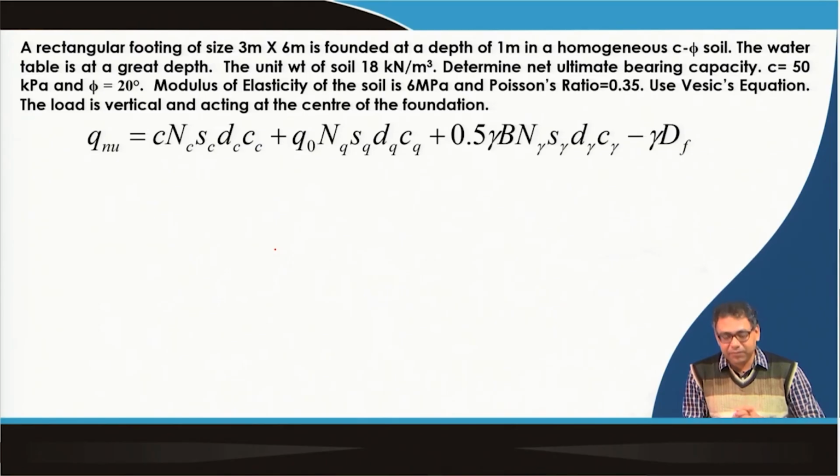But here, if we have the modulus of elasticity or shear modulus or Poisson ratio, then automatically we can understand whether this compressibility correction has to be applied or not, by calculating the critical rigidity index and the rigidity index. So, let us see whether in this case the soil compressibility correction is required or not.